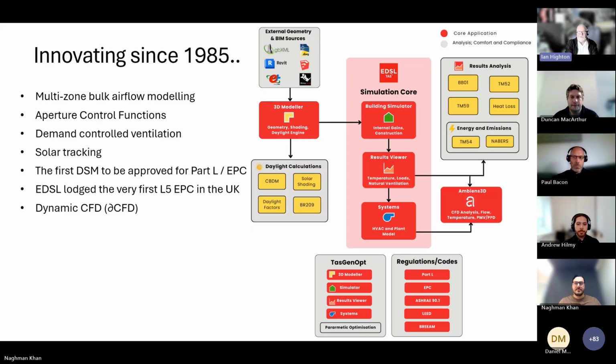So that was probably the first project where we started to get into things like demand control ventilation, etc., and subsequently, obviously, we've got many more features now in terms of how you can control those ventilation functions, mixed mode stuff, etc., which, I'll be honest, is a real pig of a thing, because you're effectively doing a naturally ventilated model, and then you have to come up with mixed mode, you have to come up with some criteria at which point you turn off the natural ventilation, shut everything down, and actually turn on the air conditioning, which again is another tricky one, to be honest.